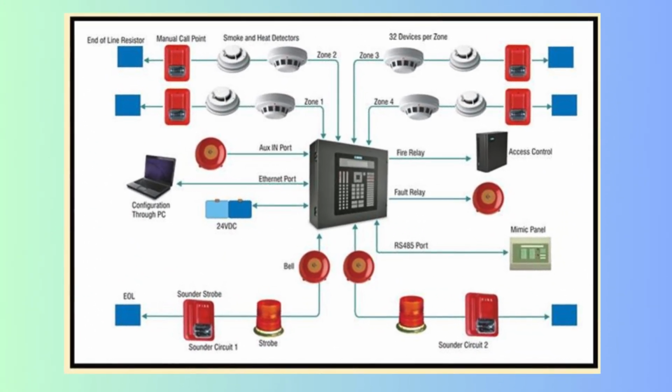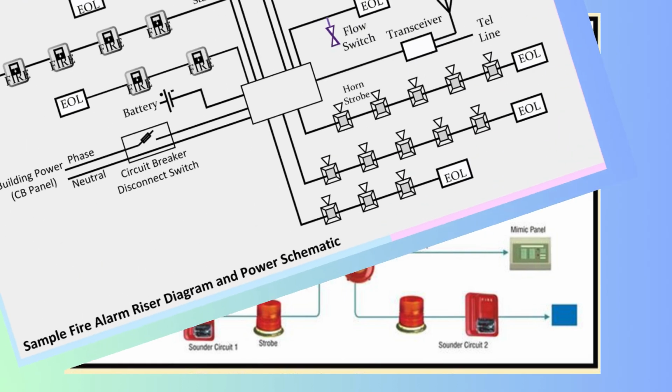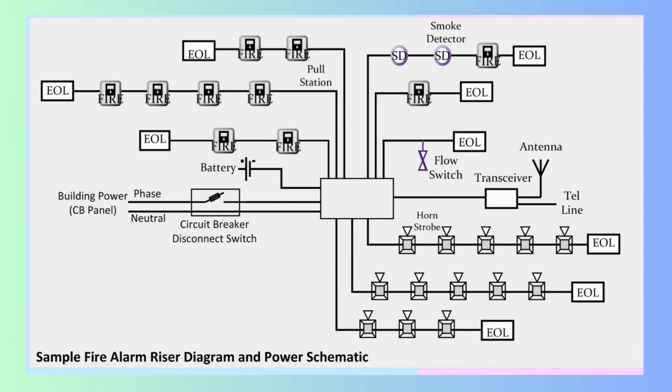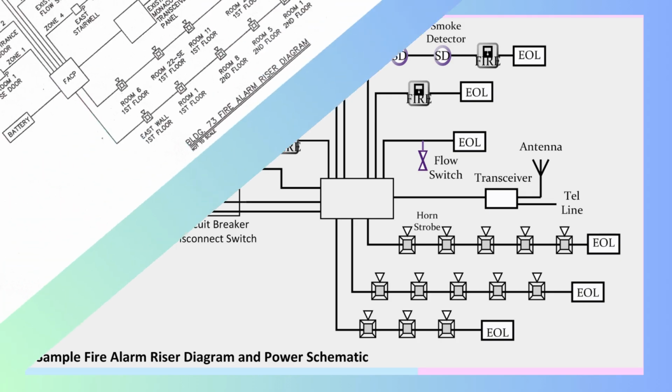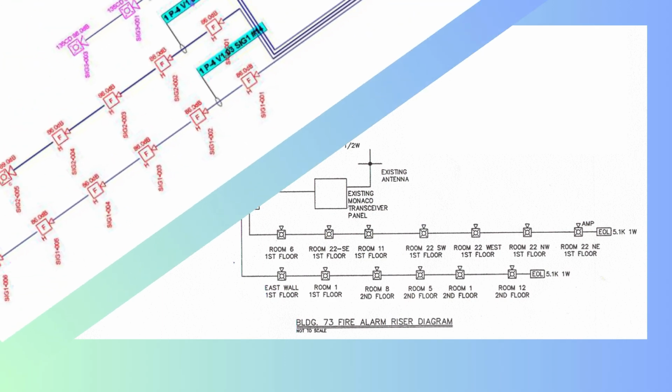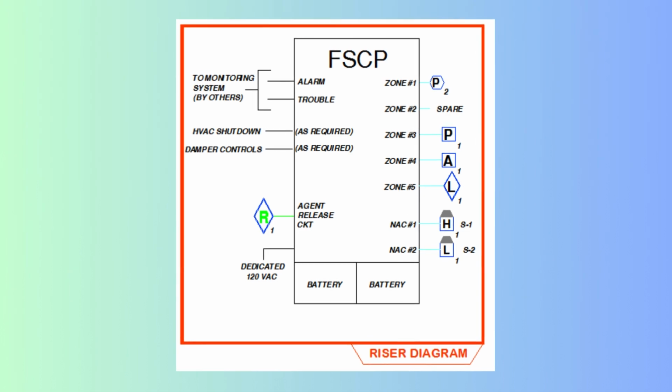A fire alarm riser diagram serves as a vital tool for both the installation and ongoing maintenance of the fire alarm system. In addition to showing the wiring paths, device locations, and control panel, it typically includes circuit design, identifying whether the system is wired in a loop (addressable) or zone-based (conventional). Backup power: detailing the connections to emergency power sources, ensuring the system functions during power outages. Device types: specifying the type of detectors (smoke, heat, CO), alarms, horns, strobes, and manual pull stations.